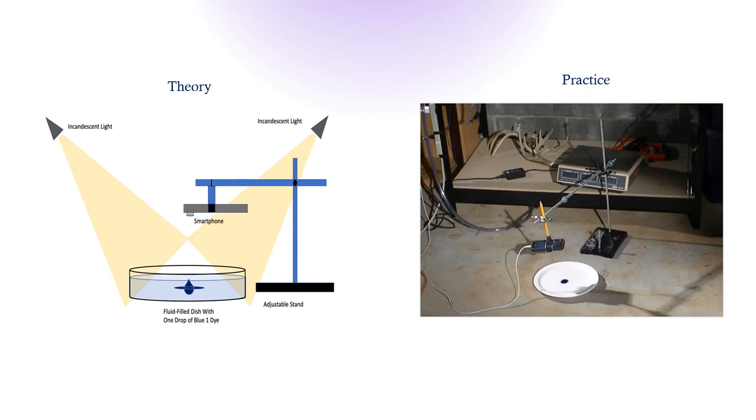We took several measures to reduce the effect of external factors on the experiment. As you can see in the figure on the right, the ceramic dish, which was chosen for a smooth surface, was placed on a concrete floor to minimize vibrations. We also used a digital level and paper shims to measure and adjust the dish so that it was within a tenth of a degree of being perfectly horizontal.